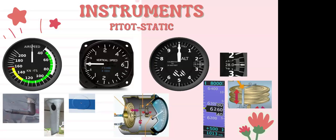So we have a direct line to the diaphragm. That means it's unimpeded as soon as we move up in altitude, which means less dense air, or down in altitude, which means denser air. The diaphragm is getting that change in density immediately.